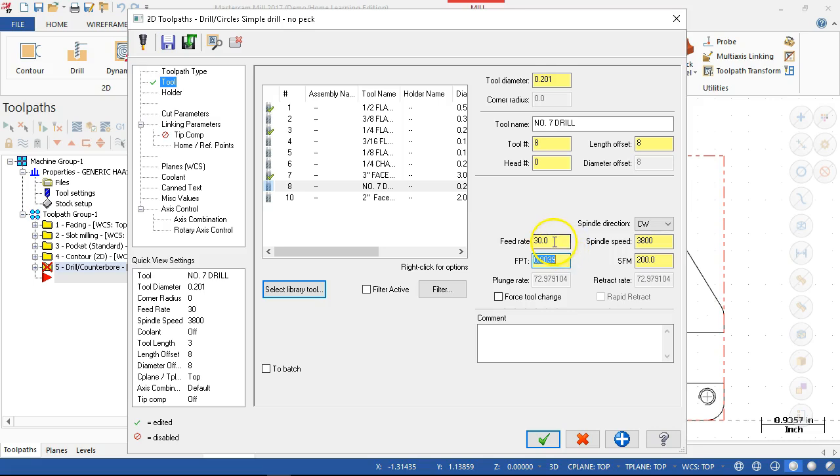So when I make that adjustment and I see a number that's still close to what the original was, 4 or 5, what I'm basically asking is, am I going to be able to stand there and watch that drill peck at 30 inches or 40 inches a minute when I would rather see it at 30 inches, and probably I'll end up slowing it down to 20 inches. So that's the juggling act right there of how bad is that drill going to squeak as it's getting through that material. At 40, it's going to be a pretty heavy squeak. At 30, it's still going to be pretty heavy, but probably manageable. At 20, whatever.